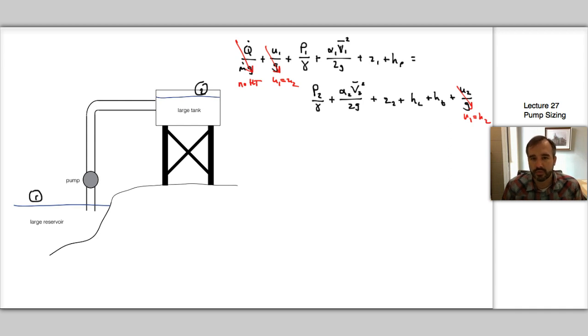So then you have to deal with the flow rates and the pressure. And so your P1 might be the pressure in the beginning of your system, and P2 might be the pressure at all the endpoints of your pump array system or your piping system for the municipal water supply, and that one needs to maintain 50 pounds per square inch.